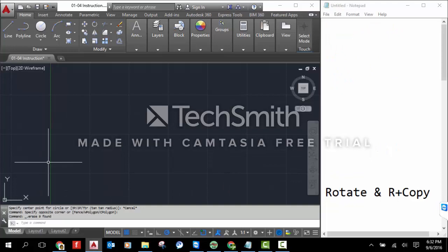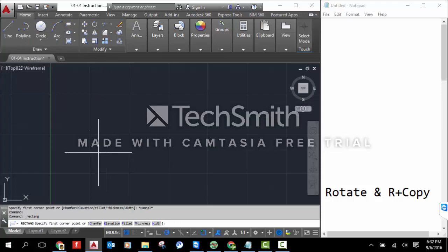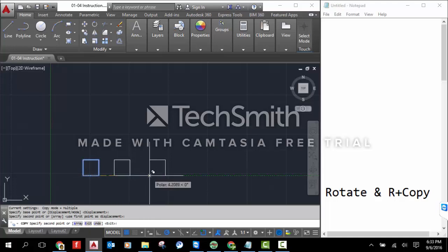Now let's talk about rotate and rotate plus copy. So what we're going to do is just grab the rectangle tool, and we're just going to draw just one little rectangle. I'm not too worried about that one. Mine's just about 1.5. We're going to use our copy tool, and so I'm going to select the object. Remember, once I've finished selecting the object, I press enter, and then now I need to specify the base point I want to copy it. I'm just going to click here and put mine out, and again, it doesn't matter exactly what we do. You'll get the idea in just a second.